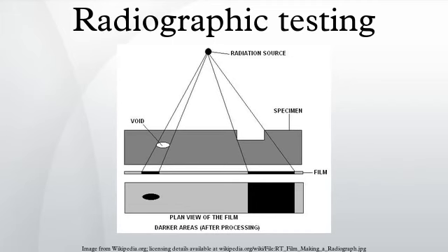Defects such as delaminations and planar cracks are difficult to detect using radiography, particularly to the untrained eye. Without overlooking the negatives of radiographic inspection, radiography does hold many significant benefits over ultrasonics, particularly insomuch that as a picture is produced, more accurate identification of the defect can be made, and by more interpreters. Very important, as most construction standards permit some level of defect acceptance, depending on the type and size of the defect.